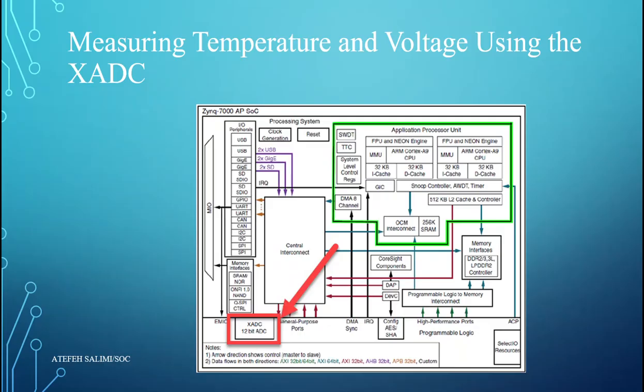This allows the CPU to connect to the XADC and retrieve measurement data without requiring any additional logic implementation in the PL. In this experiment, the focus is on measuring the internal temperature and supply voltage sensors of the chip to examine the operation of the XADC and its voltage and temperature monitoring capabilities.